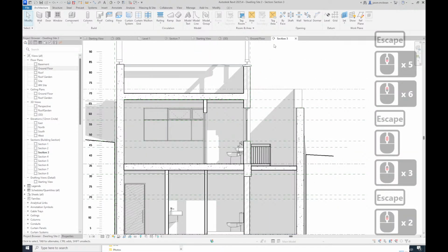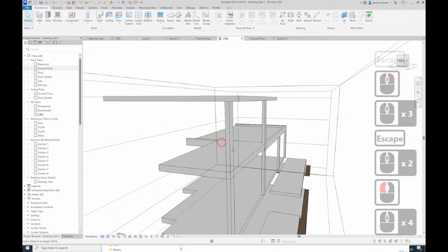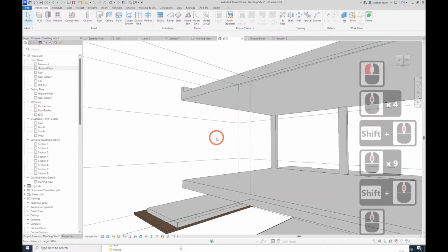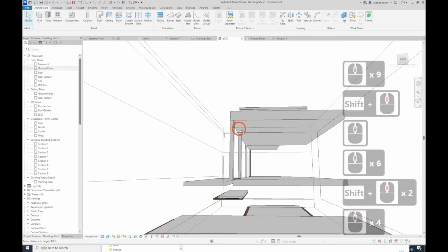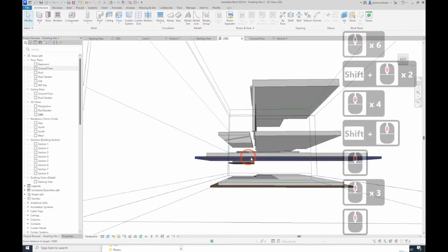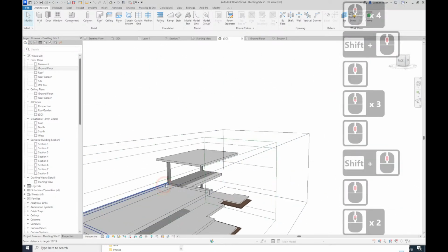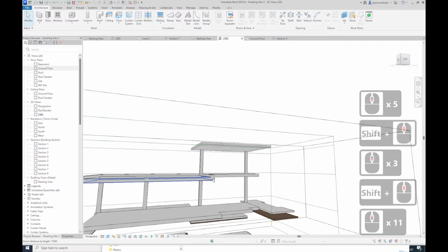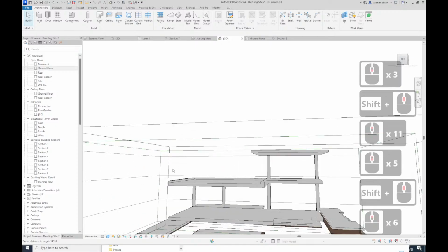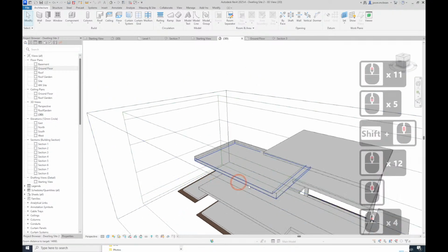So let me go back to 3D so you might see in 3D now. There. So it's an upstand beam and you see how these columns connect? And because there's a beam across here, this will connect into this concrete wall there, because there's a concrete wall there. So that's all I need to do for my structure. Because this is a concrete wall, that beam will support the edge load going across. Okay, so you can do an upstand beam or a downstand beam, totally up to you.